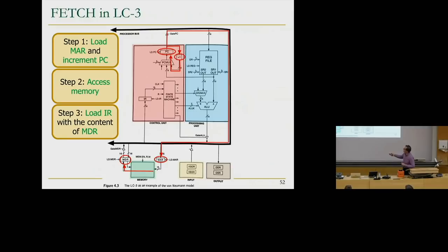How do you do that? You set this signal to 0, and you set the signal to 1, such that during that clock cycle, the data that's coming from over here gets written into the instruction register. Okay, so now you kind of have a sense of how you should set the control signal so that the elements that are designed do the things that you want them to do. And in this case, we're fetching an instruction. We don't even have an instruction yet. We're fetching the instruction from the address pointed to by the program counter into the instruction register. And that's the third step, basically.